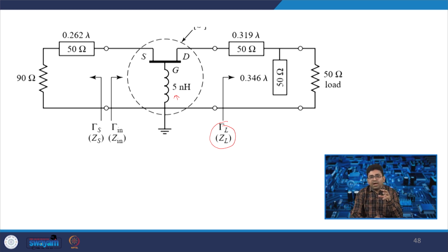So, this is how you can design an oscillator by using just a single transistor and designing the input matching network and output matching network. It has many applications, for example in RF transceiver design, where you want to design a specific oscillator. So, this is how you can design an oscillator.